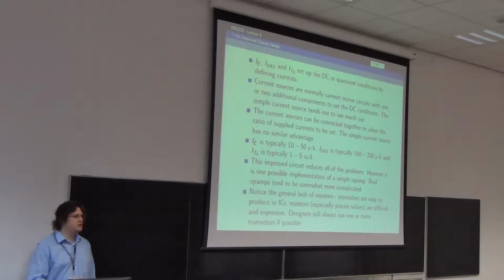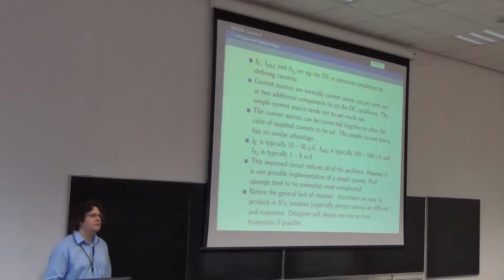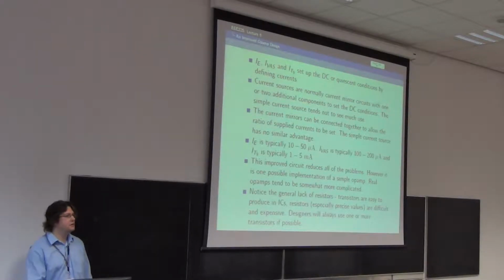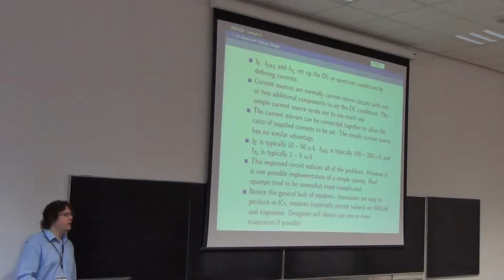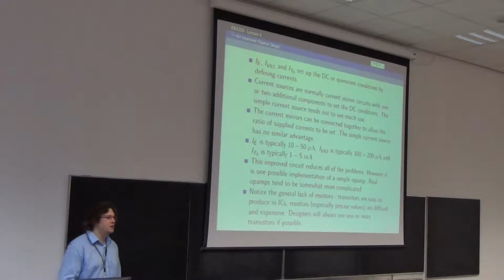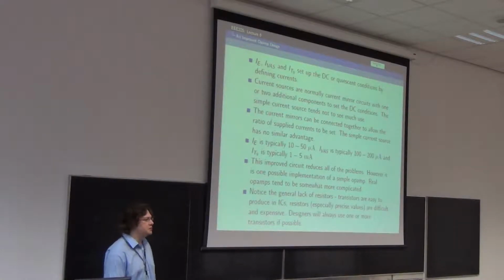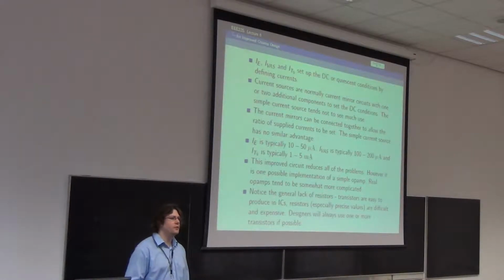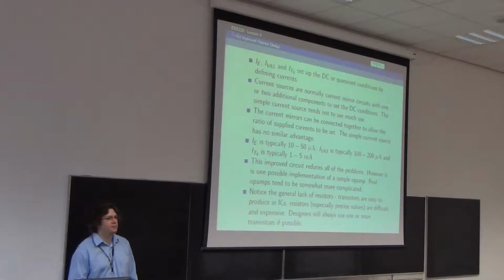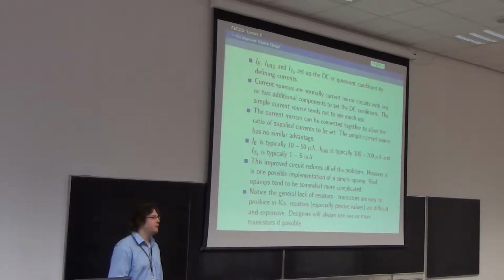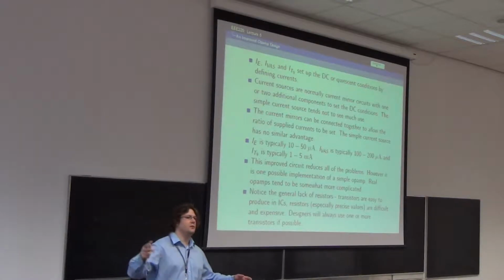And on the data sheet, the op-amp will say what it can drive. It will say full power into so many ohms. Usually you'd buy an op-amp specifically for the purpose you had. So if I knew I needed to drive a 50 ohm transmission line, I'd buy a line driver op-amp, and it would have some extra stuff that was good about it, like it could have a big capacitance hanging off its output, because a coaxial cable is just a long capacitor really.